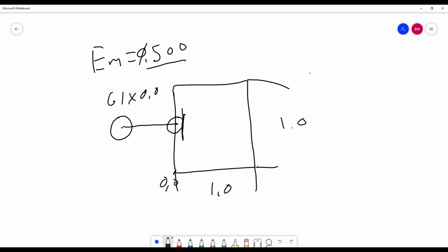But if you have an angled line, like let's say it looks like this, you can run into issues because you have to compensate here to here. So it requires a little bit of trig, and if you look in the machinist handbook, it has stuff for that. Now, that is unlikely. I'm going to go over cutter compensation right now, just while we're talking about linear interpolation, G01. Then we'll talk about G02 when cutter comp's already on. I think that'll be by far easier.